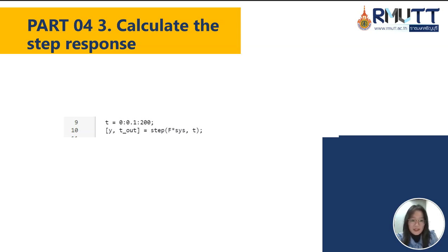Set the simulation time range and calculate the response. T defines the time axis from 0 to 200 seconds. The step function calculates the displacement response under a 500 step force, obtaining the displacement y and the corresponding time t out.